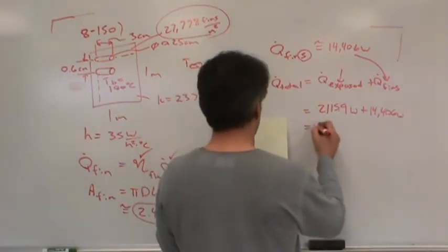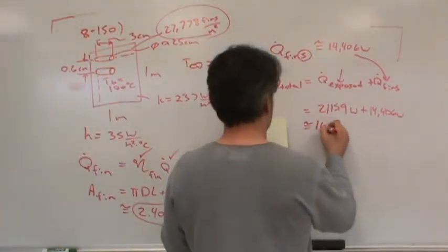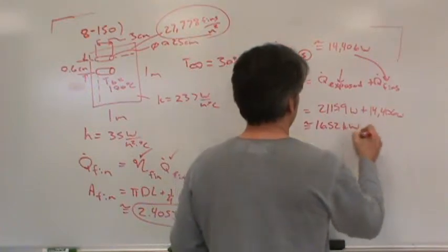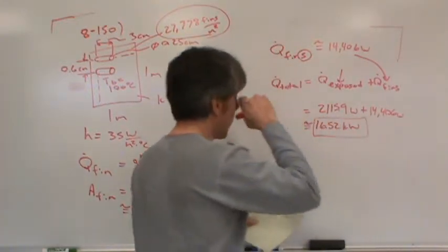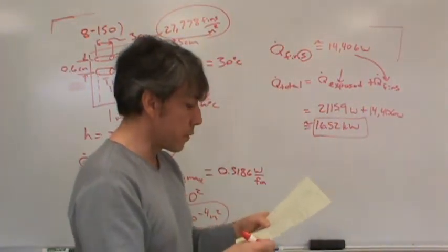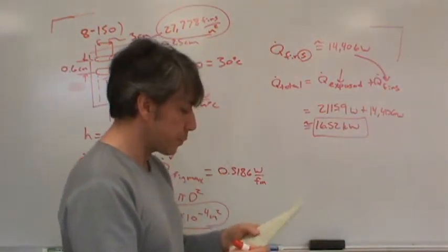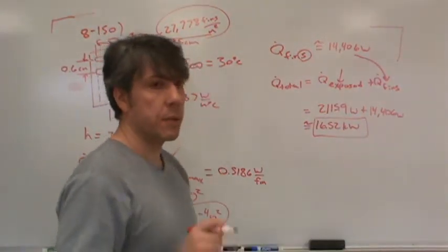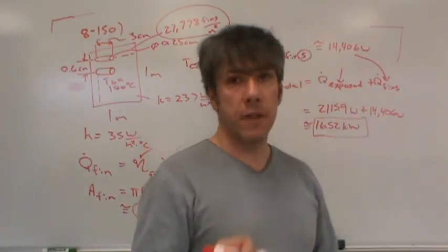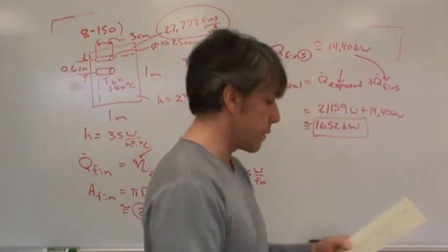Anyway, so the total heat transfer rate is about 16.52 kilowatts. Okay, so that's the total heat transfer rate from this surface with fins. Now, that wasn't what we were asked. We were asked about fin effectiveness. So how effective are these fins?